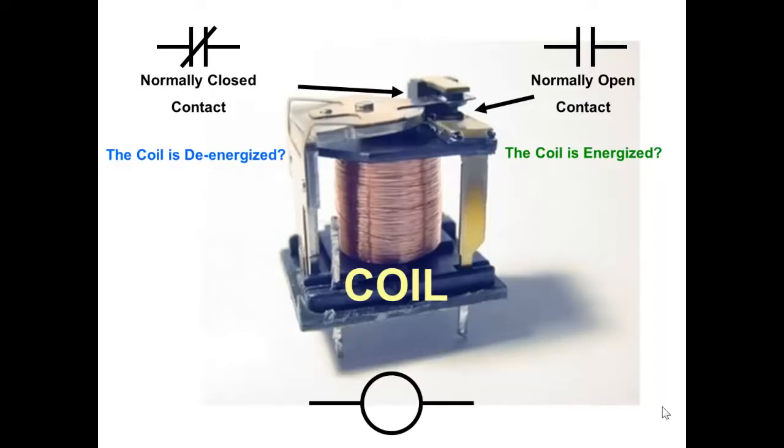So the coil then represents the state collectively of those three switches. So if in someplace else in the relay logic you want to query that coil to see if those three switches are all closed, then you would use the normally closed contact to ask the question, is the coil de-energized? If the normally closed contacts are closed, then yes, the coil is de-energized and it's true.